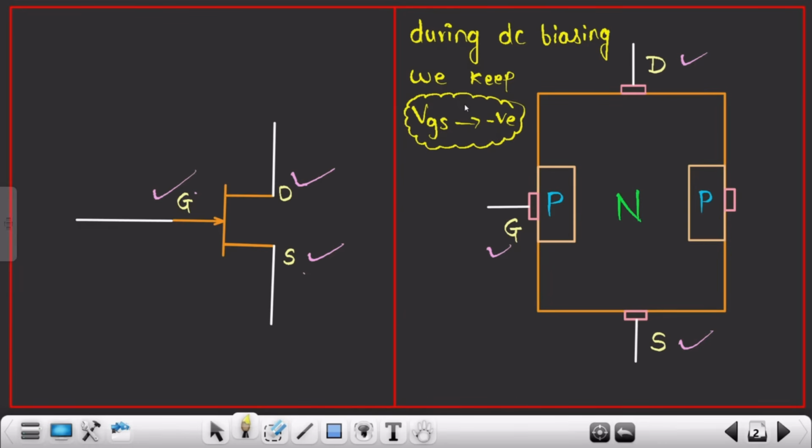This is the basic part we had seen in the case of BJT as well. This is a simple logic of superposition. If you are dealing with one source at a time, you should ground the other source, provided that source is a voltage source. If it is a current source, you have to open it. I mean, you have to replace those sources with their internal impedances. We all know the internal impedance of any current source is an open circuit, an infinite resistance, right? And the internal resistance of a voltage source is 0, so it's grounded directly. It is represented with a short circuit, right? Great. So everything is crystal clear up till here.